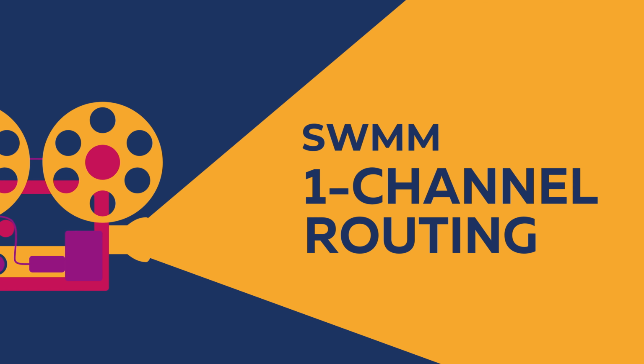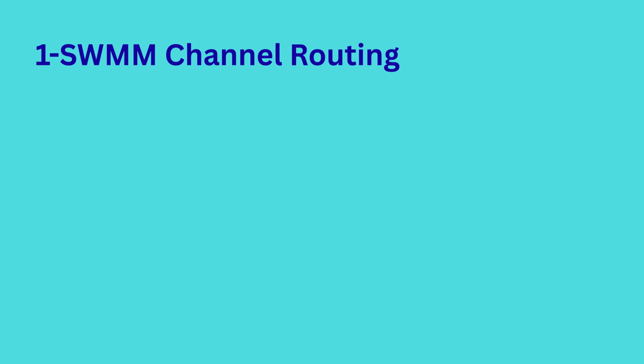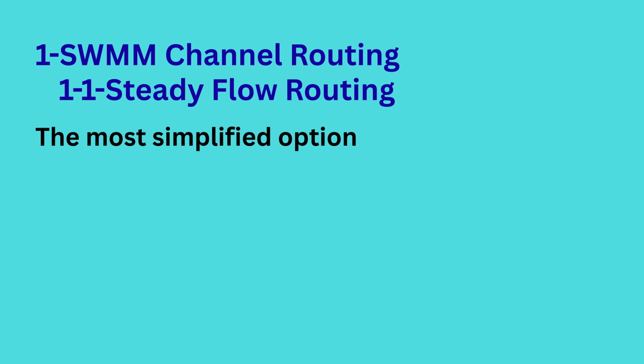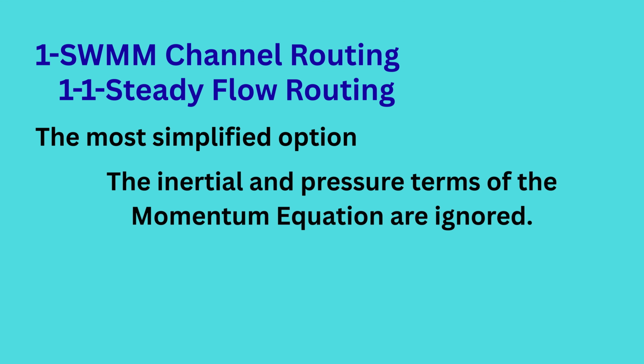Let's start with channel routing options. SWMM offers three channel routing options. First is the steady flow routing. It represents the most simplified level of hydraulic simulation available in SWMM. It ignores the inertial and pressure terms of the momentum equation.